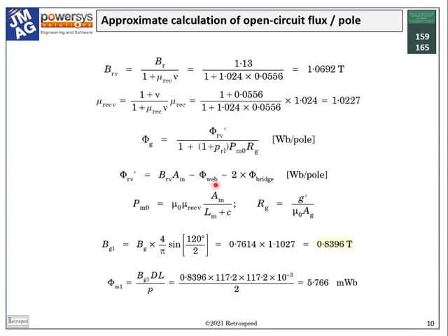If the magnet remnant flux density is, let's say, 1 Tesla, and the bridge and the web saturate at 2 Tesla, then for every millimeter of width in the web plus bridges, we will lose the flux from twice that number of millimeters in the magnet width. And here the combined width of one web and two bridges is 3 plus 2 times 1.4, that's 5.8 millimeters.